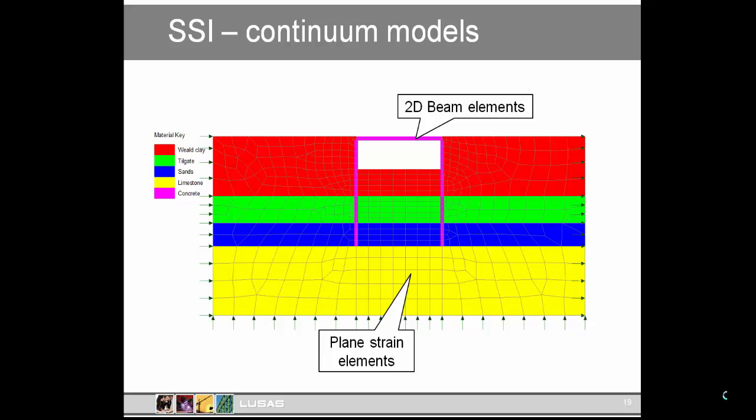As we're now modelling the soil mass around the structure, some new questions come. For example, how far out do we need to model? Where the boundaries are not defined by something physical like bedrock or a cliff face, we have to test our model to ensure that our assumptions about the location of the model edges don't introduce a significant inaccuracy. In fact, we can test if the width of the model is sufficient by changing the support conditions at the vertical boundaries.